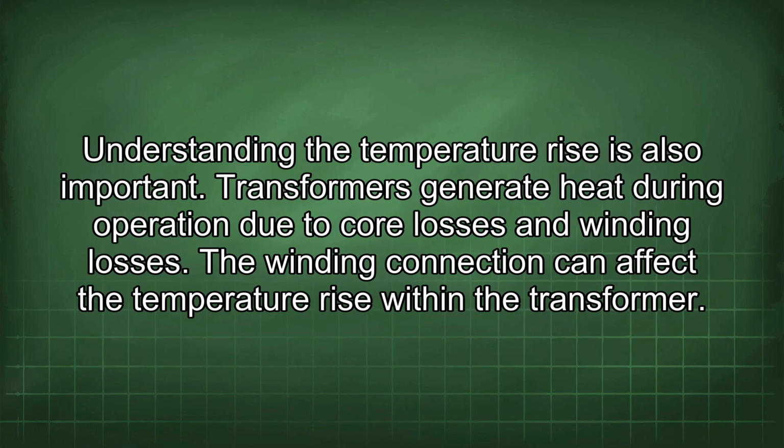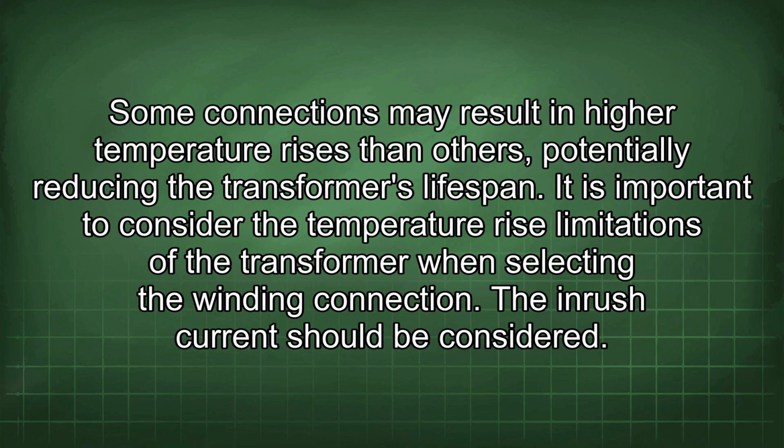Understanding the temperature rise is also important. Transformers generate heat during operation due to core losses and winding losses. The winding connection can affect the temperature rise within the transformer. Some connections may result in higher temperature rises than others, potentially reducing the transformer's lifespan. It is important to consider the temperature rise limitations of the transformer when selecting the winding connection.